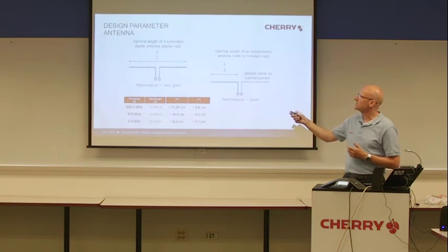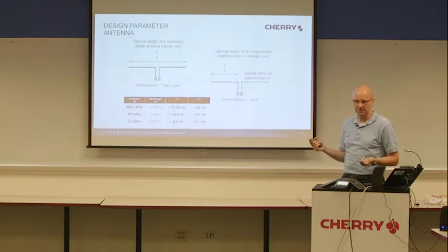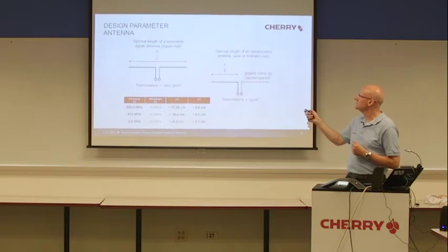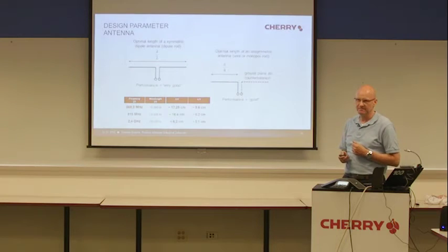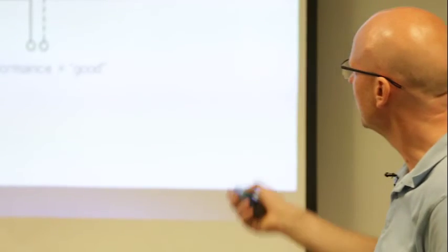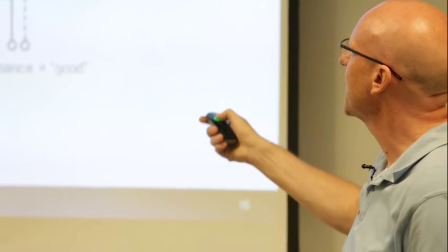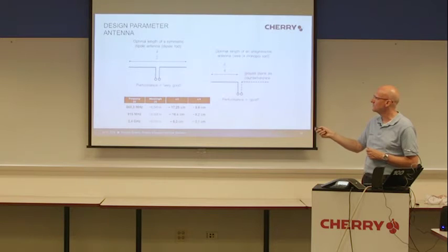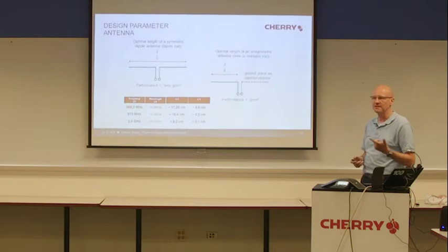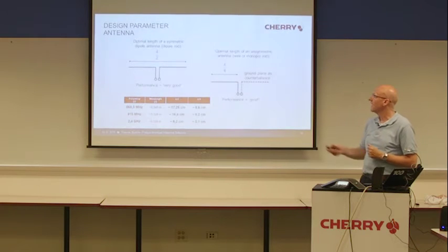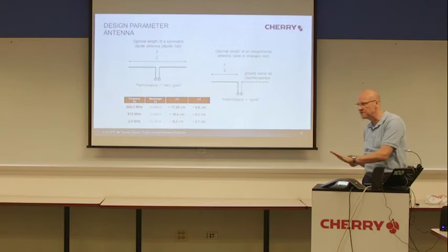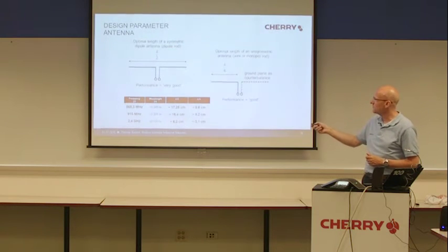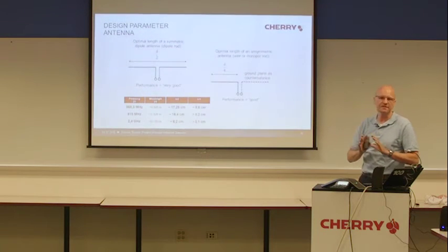And this is called a symmetric dipole antenna. So you would use two wires on your system. But you can also use a so-called unsymmetric antenna. So it's only one wire. The other pole is a ground plate on your PCB. And this is what we have, for example, in our rocker switch, in our module, in our snap switch, and also in our receiver. There is only one wire, and the other pole is on the PCB, designed on the PCB. And the performance of such an antenna, we can say, is good.